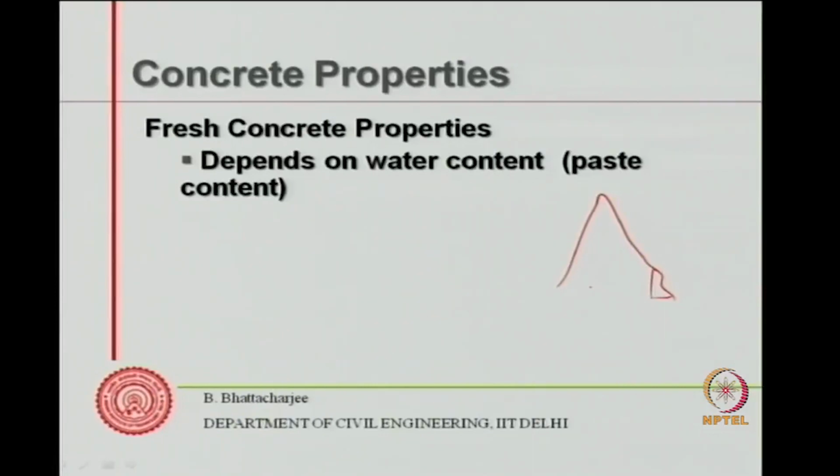Now, paste. If I vibrate it, they may not move a little bit, but not much. But if I have paste inside them, paste in the aggregate system, this paste is easily flowable because it is more of a plastic state. So aggregates and paste together are in plastic state, and it is the paste which is easily flowable. In fact, in the paste again, the water is most easily flowable.